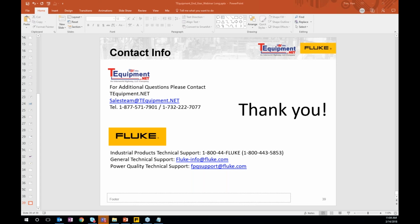Like if you want to measure torque nowadays, you'd have to take your motor apart, put a torque sensor in, put your motor back together, and then run it. And usually that's on a dynamometer in a lab somewhere. So you would have had to ship your motor off somewhere to do this. And it's fairly expensive and fairly complex. Whereas with the Fluke 438 Series 2, you basically hook up to the VFD, or if it's not operating on a VFD, just hook it up to the closest circuit breaker where the motor's getting power, and collect the voltage and current there, and the tool will tell you what the torque is and the efficiency.